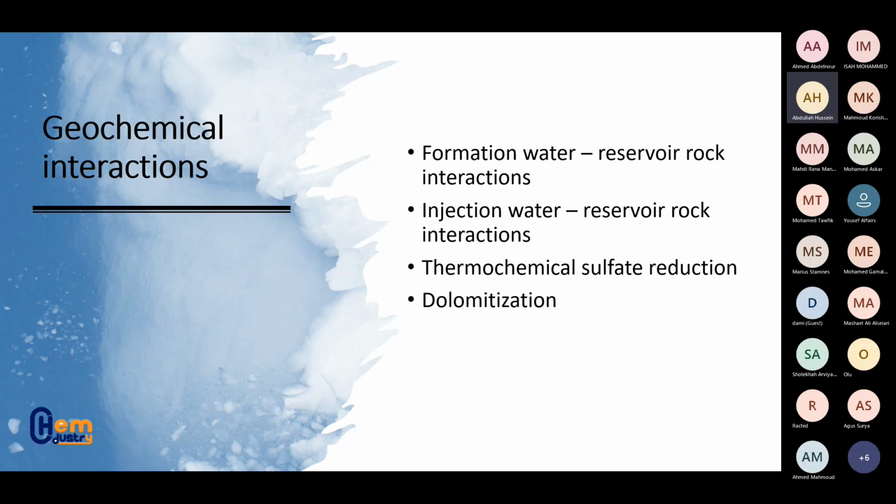Again, the problem with these geochemical interactions, this is not considered in some of the scale prediction software. So it is highly recommended whenever you do your scale prediction, if you can, involve some geochemical model with your scale prediction, just to make your calculations very accurate.